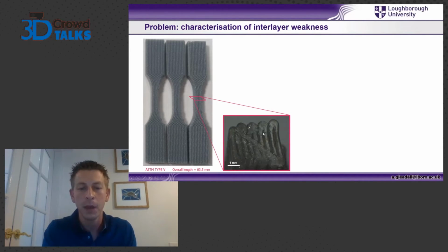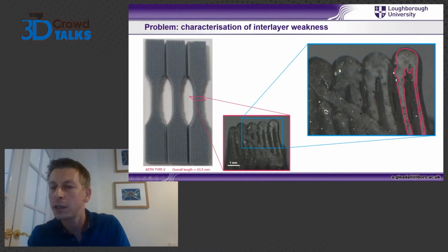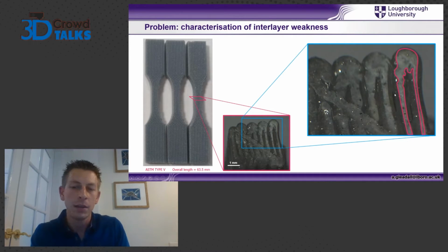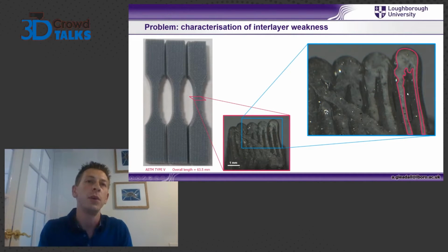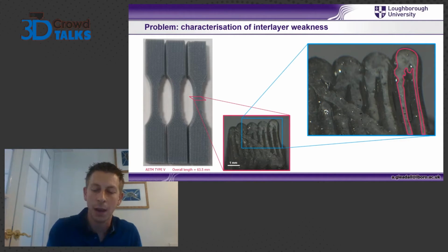And you can see this sort of weird contact area, which is a slightly lighter color on each of the filaments, and the rest, that's a slightly darker color, just hasn't been in contact with the layers above at all. So it's offering no mechanical properties from that point of view. The whole properties are really dictated by this odd contact area, which is thinner on one side, slightly thicker on the other, with a really large blobby connecting bit at the end, really uncontrolled. So it's really hard to understand what mechanical properties are happening here.